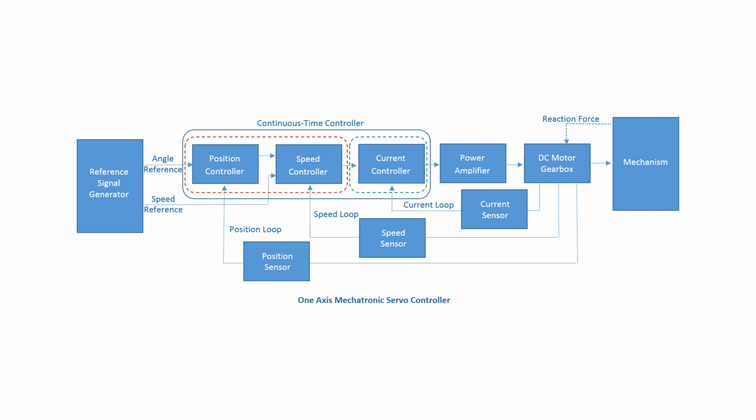This controller will also receive the actual speed signal and the position controller output. Position loop, outer: it controls mechanism angular position. In this case just a proportional controller, P, will be used. It needs the desired position reference signal and, of course, the actual mechanism position.